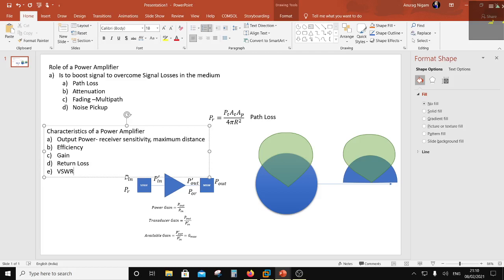Now there are two voltage standing wave ratios which are important. One is the VSWR safe operating. The other one would be called performance. What it means is that if the PA sees a mismatch on the antenna, what is the maximum mismatch which is tolerable, where it still performs despite the mismatch? That will be VSWR performance. It can be 2:1, 2.5:1, or whatever.